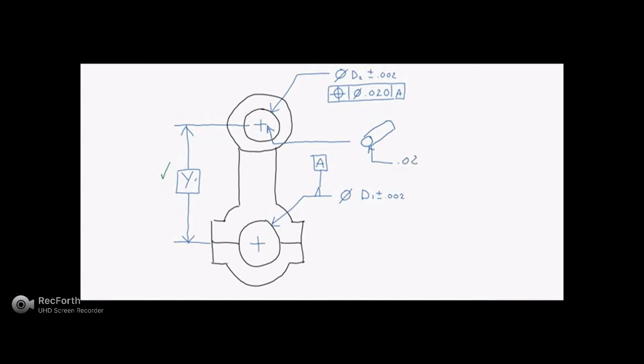It is diametric by 20 thousandths, and the length is equal to whatever length that as-built hole D sub 2 is. So what this does say to us is that our as-built hole feature D sub 2 could be drilled such that the start hole is at one end of our diameter, 20 thousandths diameter, and then as we drill through the material, that our as-built hole axis deviates throughout that 20 thousandths. So this isn't good enough.